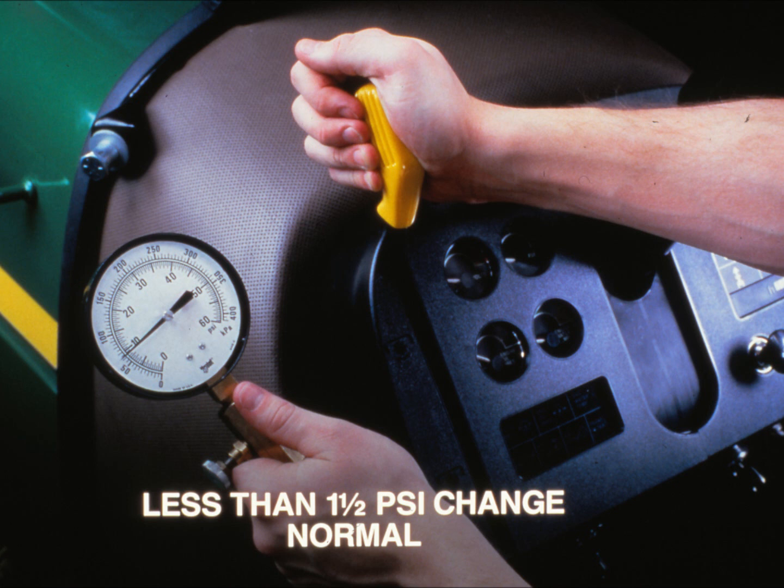If lube pressure changes by less than 1 1/2 psi, the PTO and MFWD circuits are normal. You can proceed to the next test. Changes in lube pressure greater than 1 1/2 psi indicate leakage in a clutch or brake element circuit.